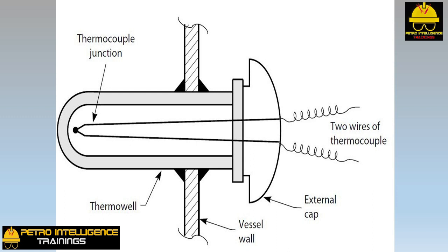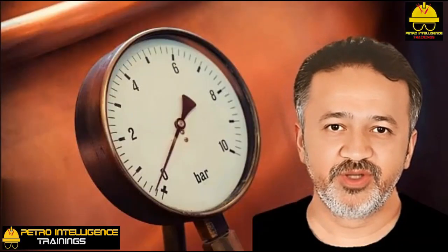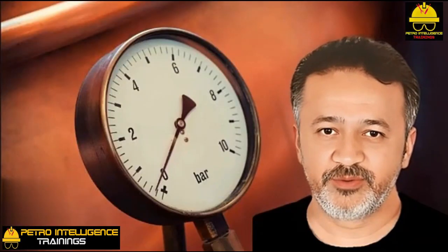It is not uncommon for a thermocouple, regardless of the type of junction, to generate too low a temperature signal. If the exterior of the thermowell becomes fouled, the indicated temperature generated by the thermocouple will drop. The problem is that the external cap of the thermowell assembly radiates a small amount of heat to the atmosphere. Normally, this has a negligible effect on the indicated temperature. However, when the process temperature is 600 to 800 degrees Fahrenheit, the thermowell is in a vapor phase, and the thermowell becomes coated with coke. I have seen the indicated temperature drop by 40 degrees Fahrenheit below its true value.